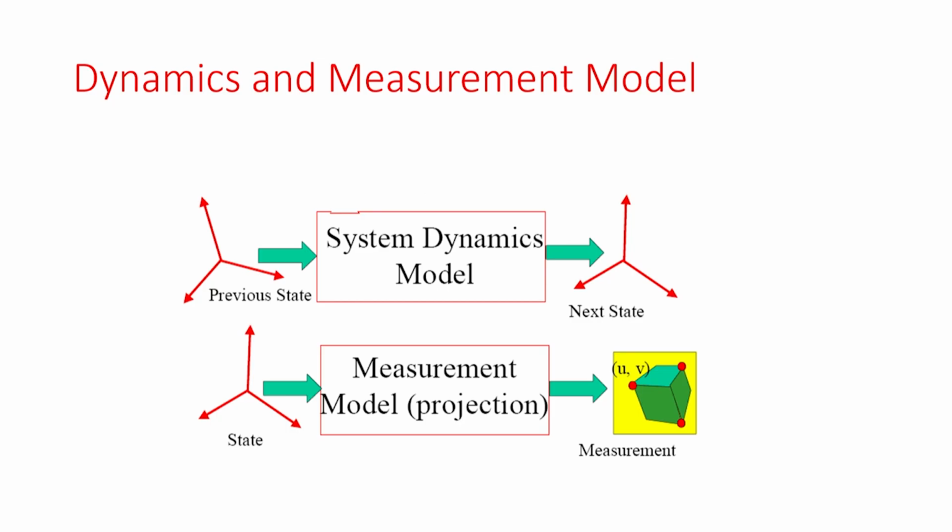First, you know your state space equation. What does the state space equation say? x dot equals Ax plus Bu, and y equals h of x. If you have some noise, it will have w, and on the measurement it is v. So, this is your simple state space equation. What is state? States are the minimal number of variables of system behavior, which represent the system dynamics quite well. And states which are measurable are your measurements, so you can write it as y, or term it z.